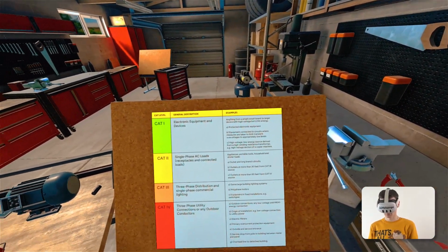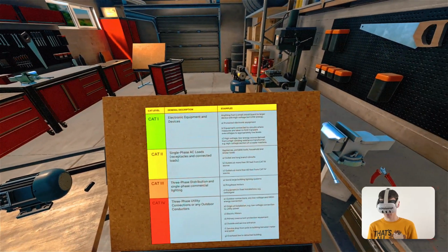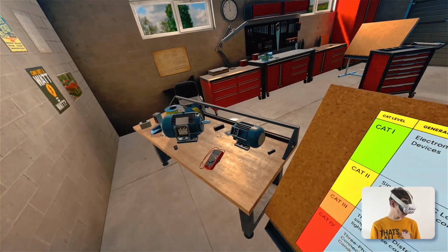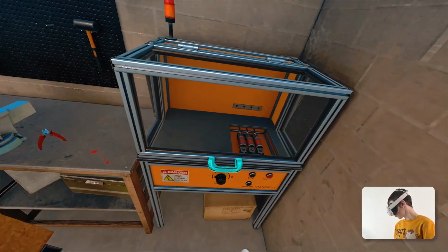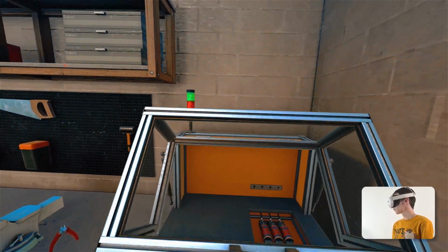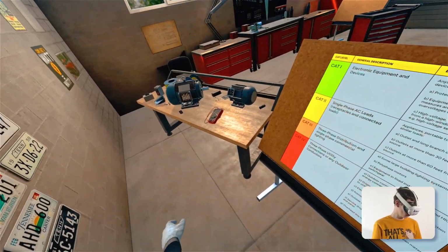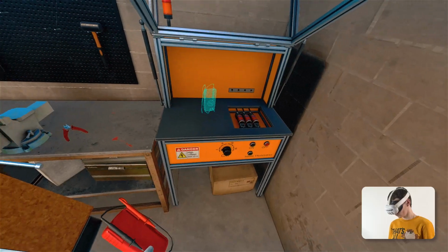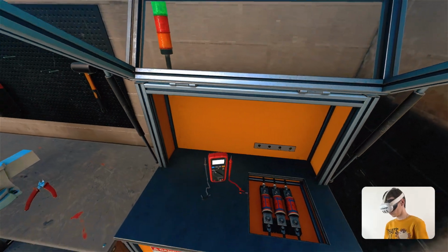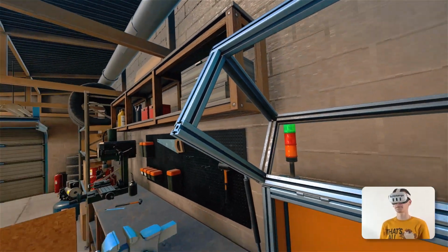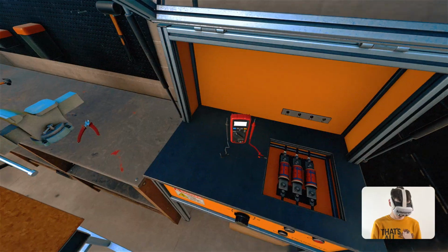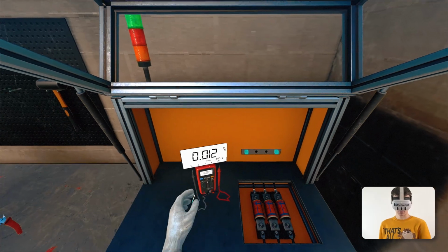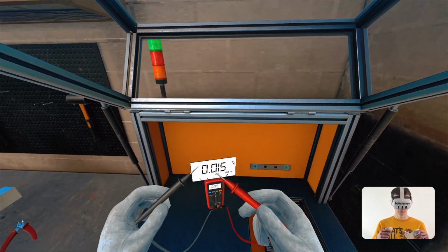Let's put theory into practice using our CAT environment-controlled simulation cabinet. On the table, you'll find a CAT 2 rated multimeter. Pick up the multimeter and place it inside the testing cabinet. Now, set the multimeter to a voltage function and connect the test leads to the corresponding input jacks. Connect the probes to the live and the ground testing outputs.